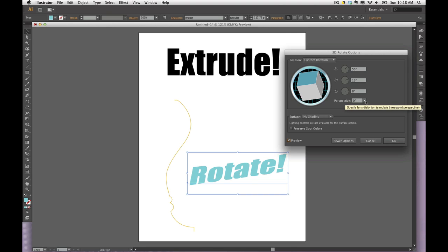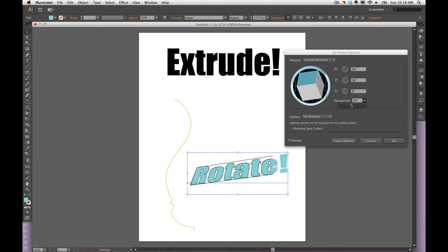But if I put in an angle in here, get it to be more of what we would see with our own eyes or with a zoom lens or something, I'll set it around 60 degrees. You can see that this edge of the lettering is more tilted than the lettering as it comes over to the side. So it's going to diminish into space, and off here, somewhere up here, it would hit a vanishing point, just like a 3D that we think of.